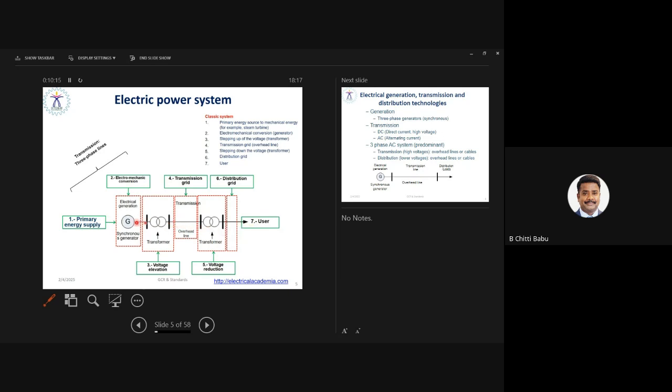That happens only in the generating power plant by simply regulating the input fuel that is being given to the generator. That is what we use as a governor mechanism. With the help of this governor mechanism, we are able to regulate the fuel input to the generator, the mechanical power, so that we are able to control the output electrical power in terms of voltage and frequency.